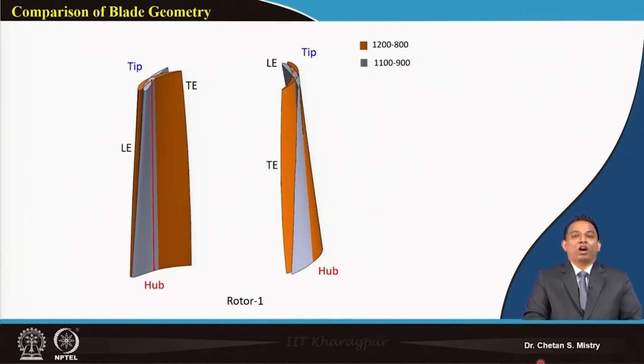Then we were discussing how we distribute our total pressure along the span at 3 different stations, such that we take care of all the constraints we have defined, maybe in terms of diffusion factor, de Haller's factor, and camber angle, for these kinds of configurations.